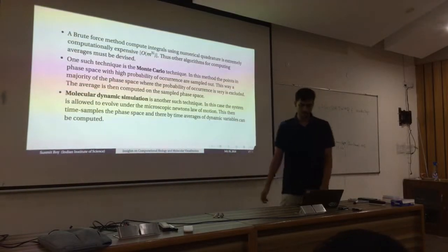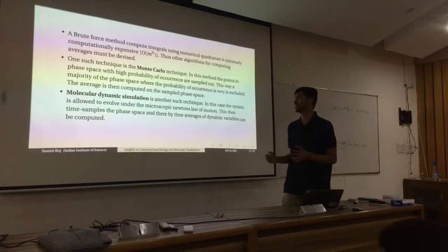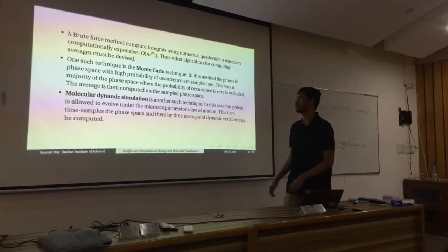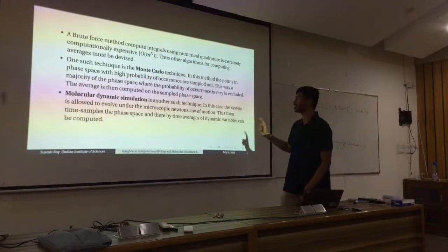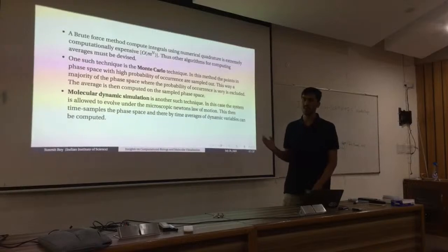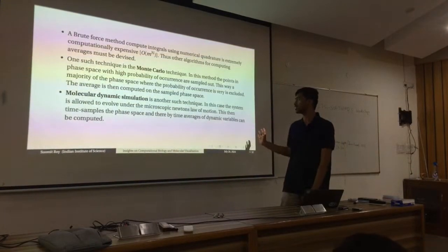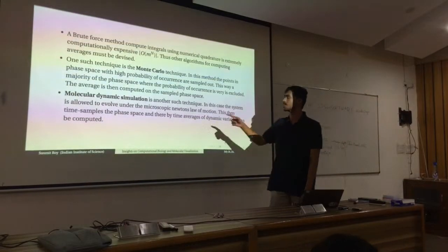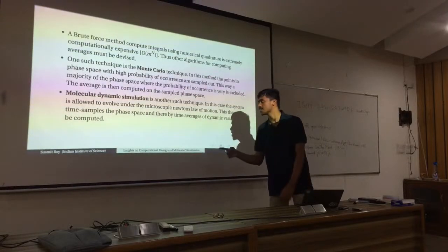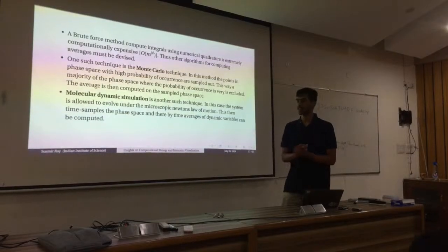So for resolving this, there are two techniques which are largely used for molecular simulations. One is the Monte Carlo technique, which samples only those points in the phase space which have large probability and neglects all the others, and the average is computed with these sampled points. And the other is the molecular dynamics simulation, which I'm going to talk about more, which finds its time